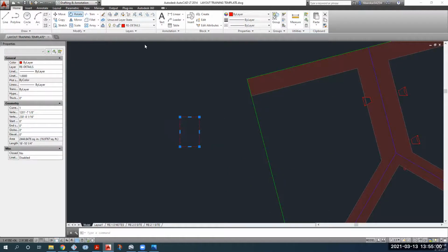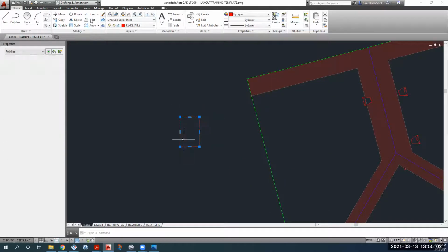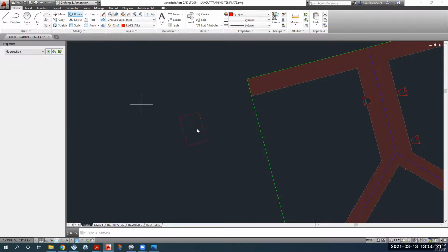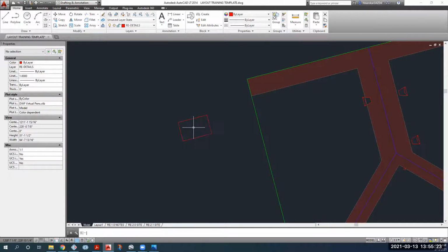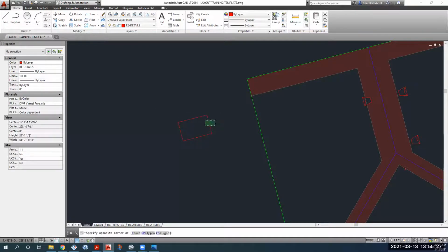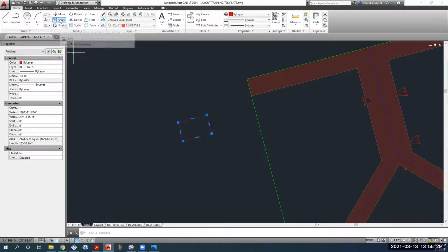Then you can use the rotate tool, select this, go rotate, select any corner, okay, and then it starts rotating things using that corner, and then you can snap it perpendicular to this line, okay. So now at least this edge has become parallel to this edge, right? Okay. So now what we do is we simply need to rotate it again by 90 degrees. Now again, I showed you how to offset things by a little bit.